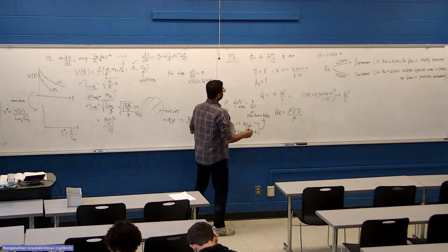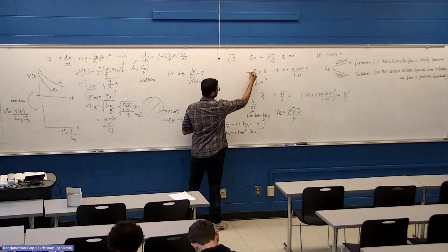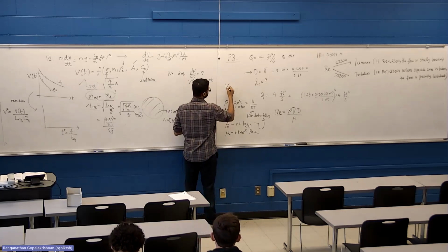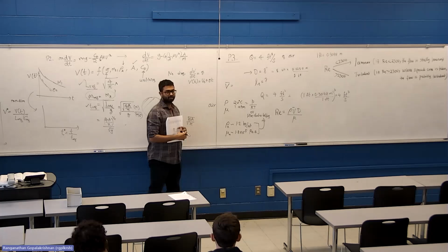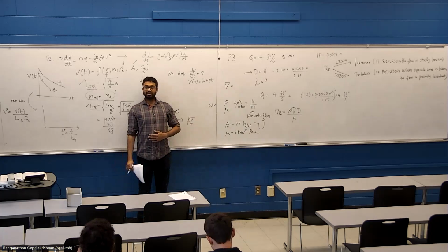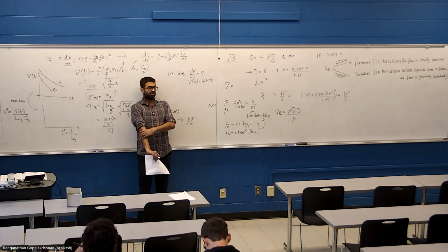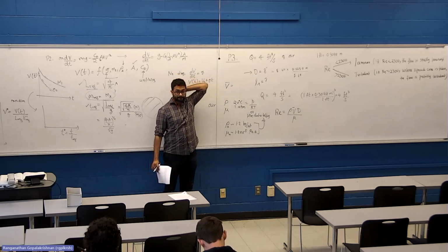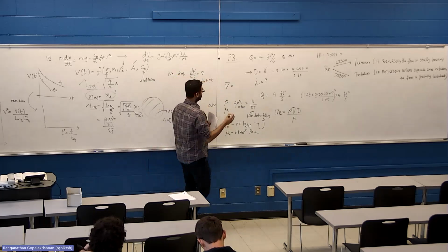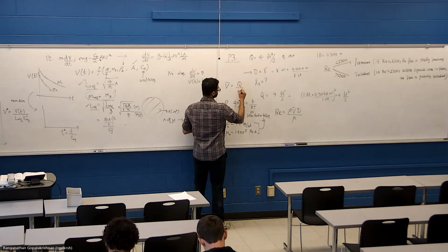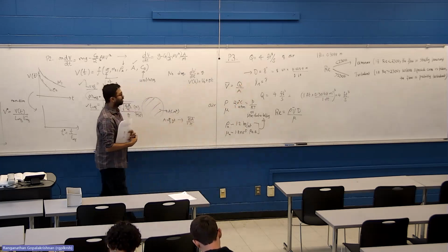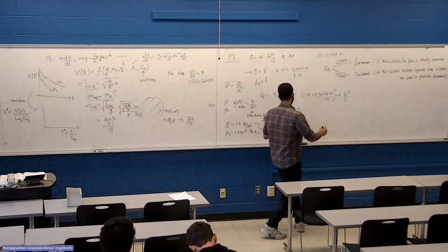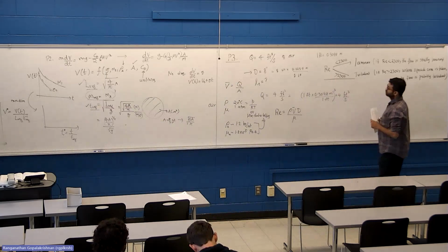And what is V? We know D. It's given in the problem as 8 inches. And what is V? The nominal velocity. What's a good nominal velocity here? For pipe flow, if flow rate is given, what's a good nominal velocity? Q over A. Average velocity, right? Q over A. So you can calculate those. So you plug in everything and then get Reynolds number and then make this decision.